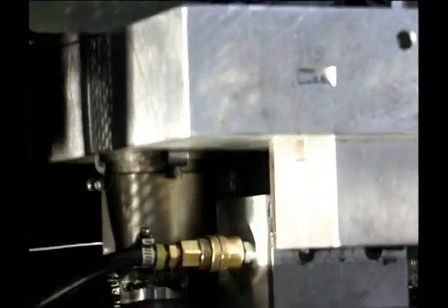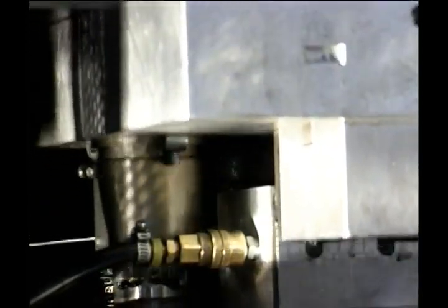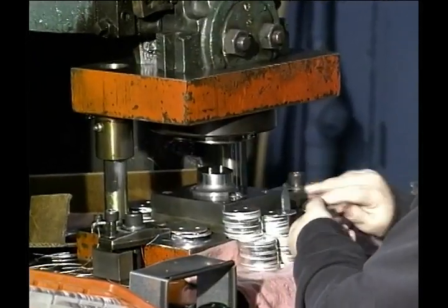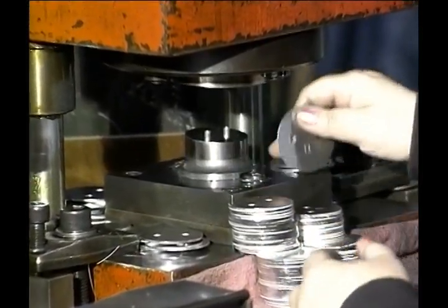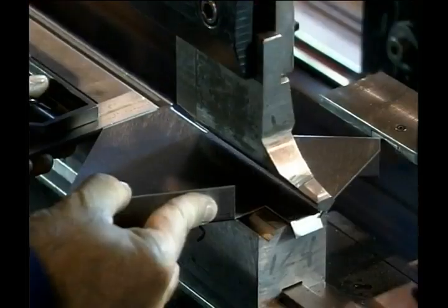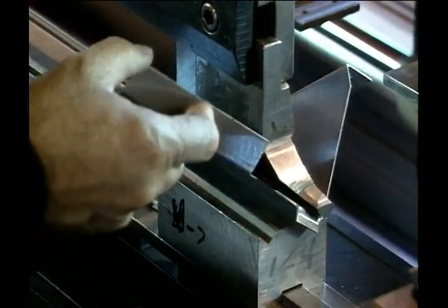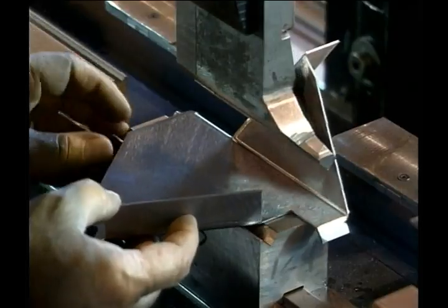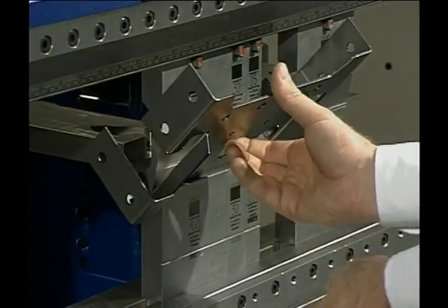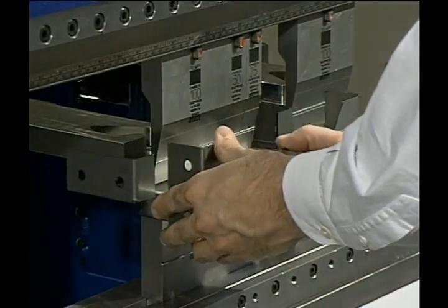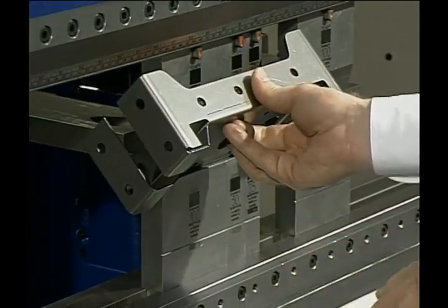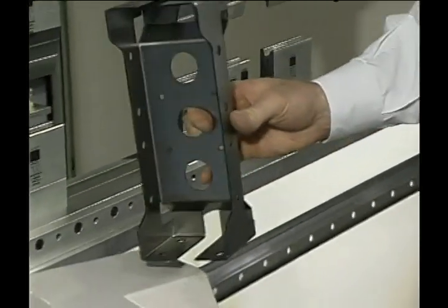Shearing is also utilized to cut sheet metal stock around the complete perimeter of a shape to form a workpiece known as a blank. These workpieces are then used in operations such as forming, punching, and trimming to complete the part. Bending is the creation of three-dimensional shapes out of two-dimensional material. Bending is a fast, economical way to produce an endless variety of parts from sheet metal and plate, often without the need for secondary forming operations.